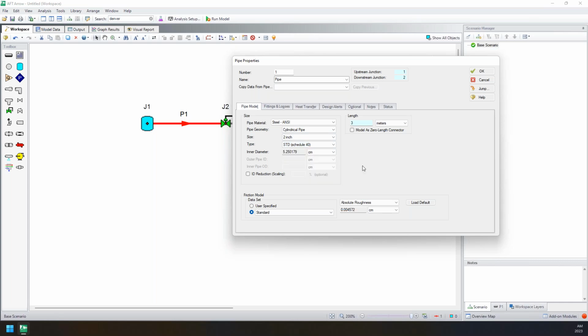Note that in compressible flow, it's also common to flow through ducts rather than purely cylindrical pipes. You can either user specify that information as a rectangular duct, specifying the height and the width, or there are some customary databases for rectangular ducts within these provided databases. So here we look at a 10-inch by 4-inch, and again, a range of different gauges, which could impact the size, or I believe it can impact the roughness as well.